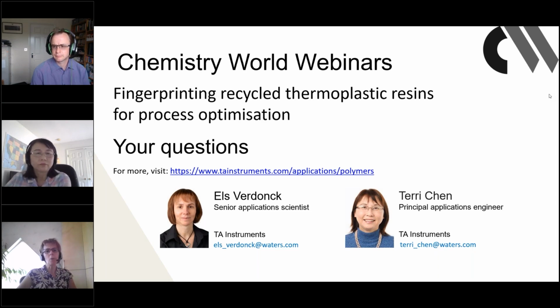And if you then couple your TGA to a mass spectrometer or an infrared spectrometer, you can then additionally with the spectrometer qualify what are the decomposition products that are being released and try to find from those decomposition products what is the native contamination.